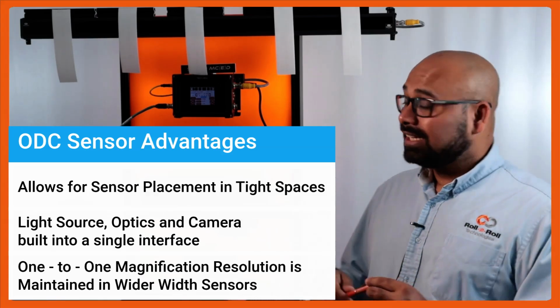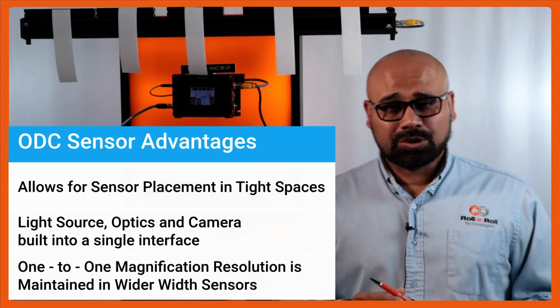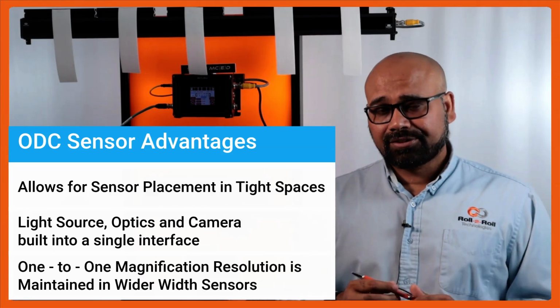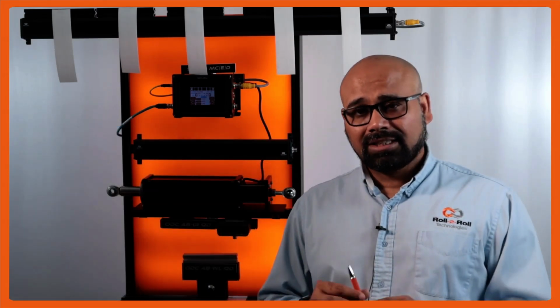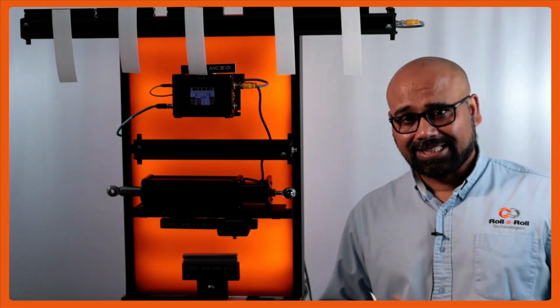So for example, this ODC 960, which has a measuring range of 960 millimeters, can provide a resolution of 127 micron on the camera level. And then with sub-pixel, you could get up to about 33 micron resolution. Your resolution is not affected by the field of view that you are requiring. Because of these advantages, the ODC sensor is used for a lot of different applications, especially in existing slitter rewinders where you want to measure the width of the material.